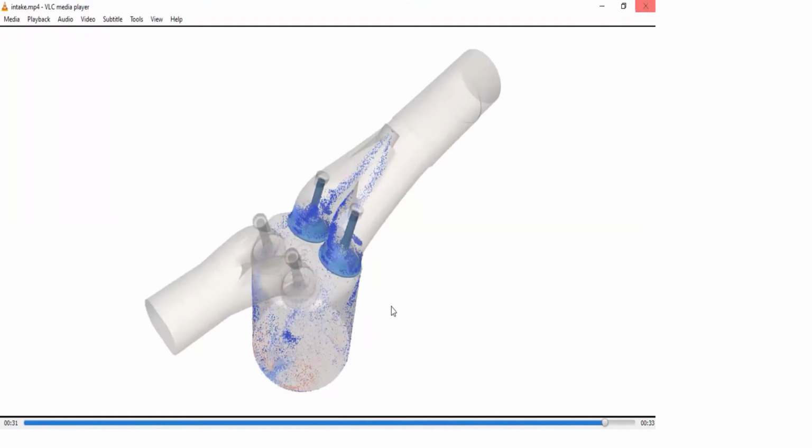Sir, how can we specifically say this amount of molecules are coming inside? Exactly. So for that, that's actually a 2 weeks project, the major project in IC engine. Usually people run the dry case first. They don't use fuel first. They will use air, and they will run for 20-30 cycles, and they will see how much air is getting trapped first in the cylinder region.